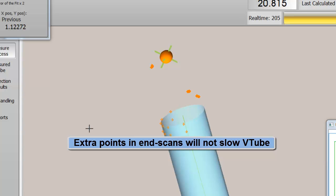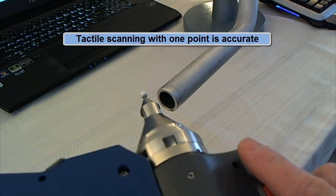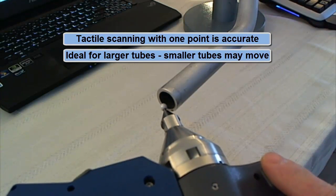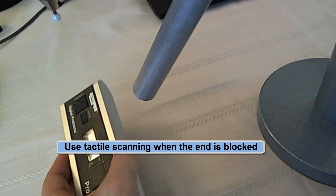The extra end scan points will not slow VTube down. Tactile scanning even with one point is accurate, but tactile is ideal only for larger tubes. And finally, tactile scanning is always used when the end is blocked by a surface.